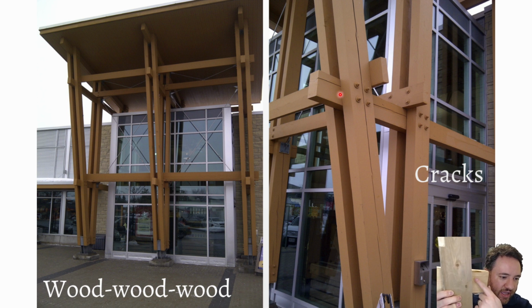Now the one behind, which the bolts also go through, does not want to shrink and expand in that direction, right? So the one at the back is going to hold those bolts in place, while the one in the front is going to try to shrink. And so as the one in the front tries to shrink, we're going to get a tension stress in between the 2 bolts, and that tension stress is going to create a crack in the middle, if those 2 are too far apart, for example.